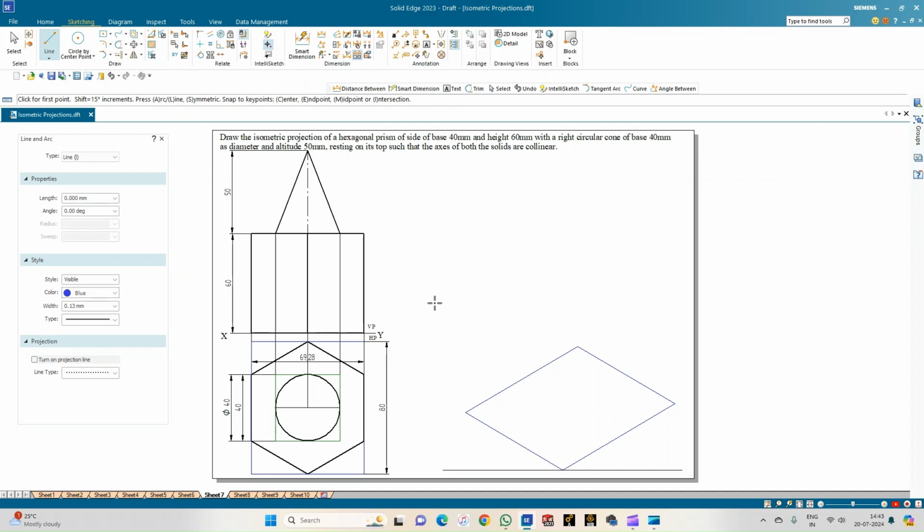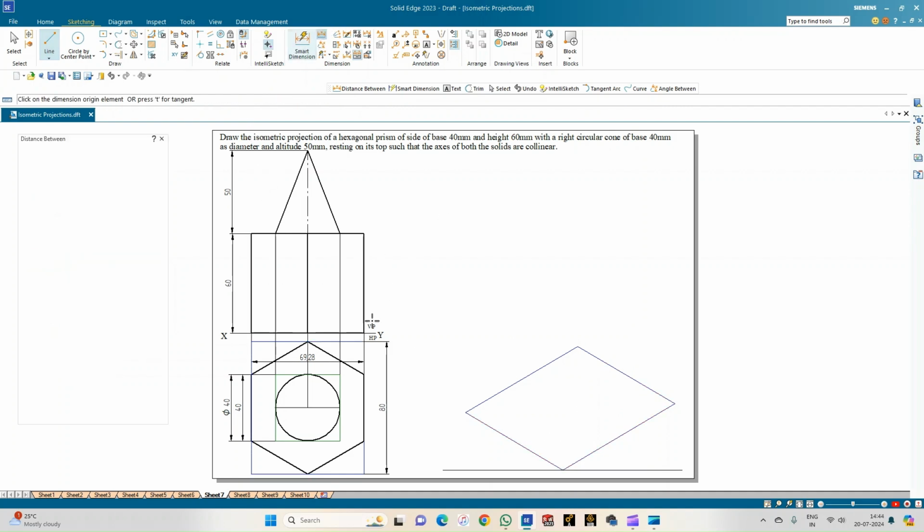How do we identify the points? So on this 80 mm line, I've got the 2 points, which are symmetric about this also. And the end point here is nothing but the midpoint of this line. So that is the location of the endpoint. So this point and this point can be located as the midpoint of these two lines of length 69.28 mm. And here I need to measure this. So let me go for the distance between.